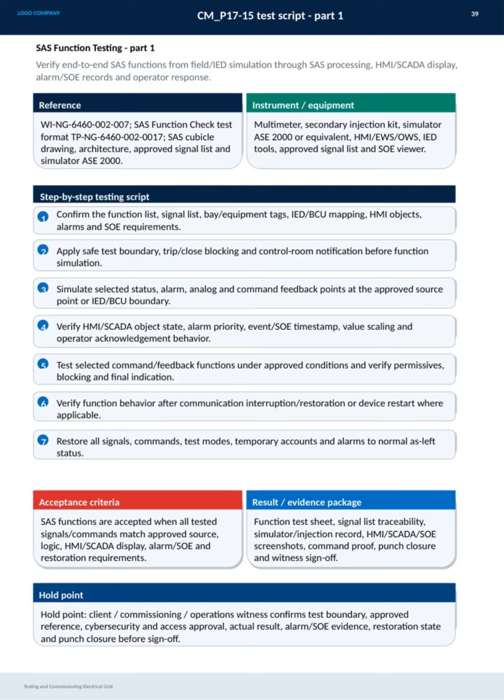Before sign-off, a hold point ensures client, commissioning, and operations witnesses confirm the test boundary, cybersecurity and access approvals, test results, alarm and SOE evidence, restoration state, and punch list closure. This thorough approach ensures the SAS functions operate reliably and safely as designed.